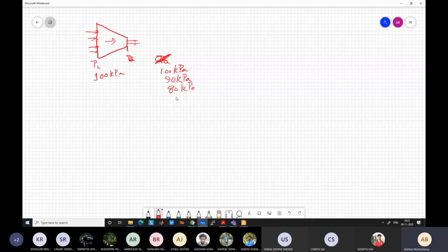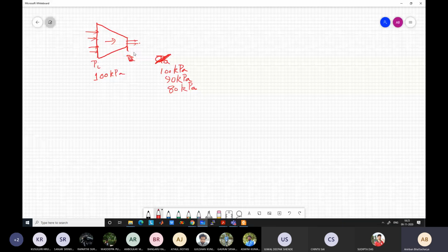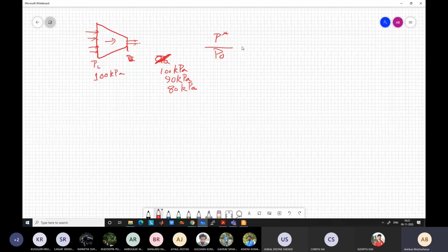We have discussed this. Can somebody say at what point? Choked pressure, sir. At choke pressure, the critical pressure. So there is a critical pressure ratio, P star by P naught, which is given by 0.588 or something like that we had calculated. I don't remember.